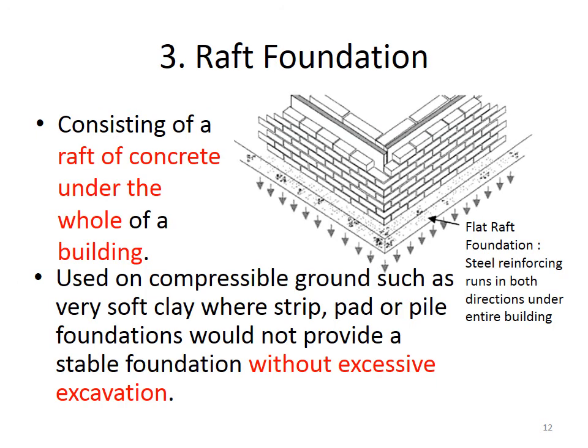Number 3 then, the raft foundation. So consisting of a raft of concrete under the whole of the building. It's used on compressible ground such as very soft clay, where strip, pad or pile foundations would not provide a stable foundation without excessive excavation.